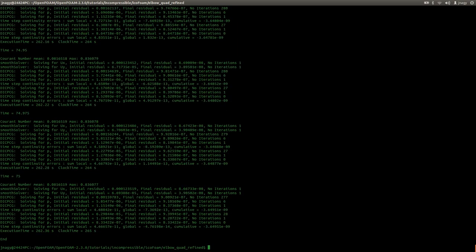Okay, now the simulation stopped. It ran until 75 seconds. It took a little bit longer. And now you see that the maximum Courant number is 0.83, so there is a definite change. Now, let's just open up this case.